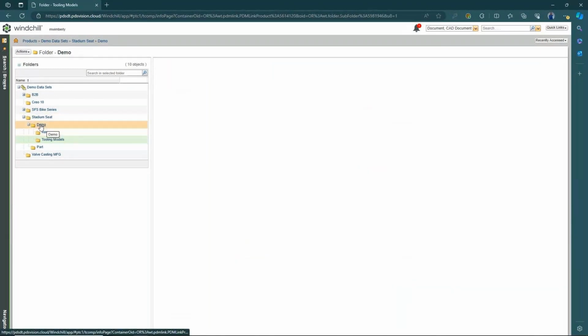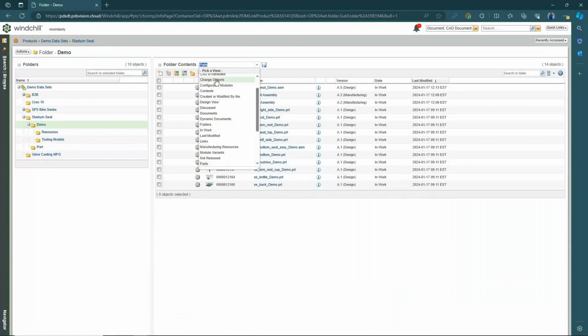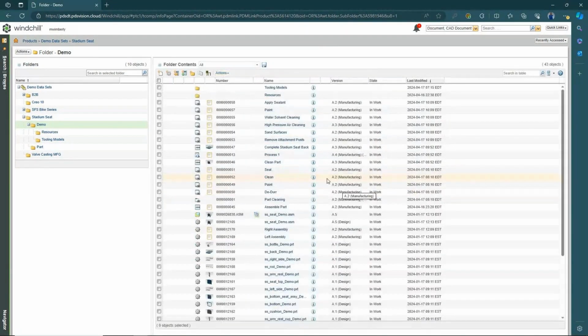As I said, we started at one level defining multiple things, and then we began to define additional objects: resources as well as tooling models that we want to use. A lot of what we need to do is pre-work. The process plan is the last piece, and it's actually one of the easier things to do, but we want to make sure we capture everything necessary. We want to make sure we have our mBOM, our locations, our tools, our skill sets. So when we start building up our process plan, we're just plugging them in: here's process one, it is associated with this.